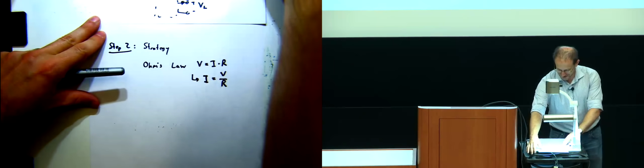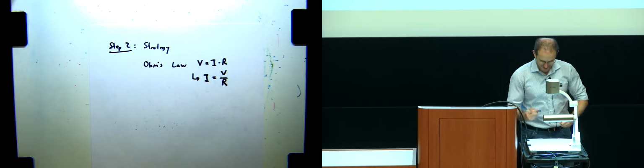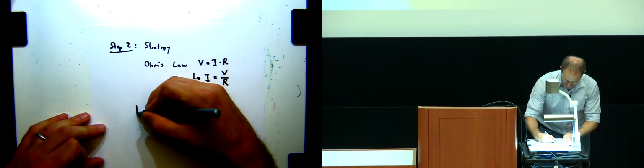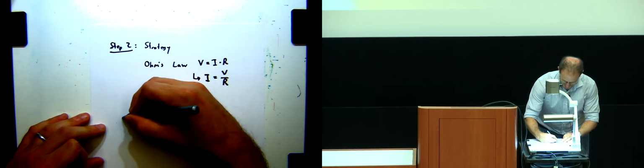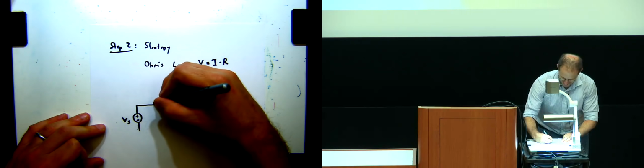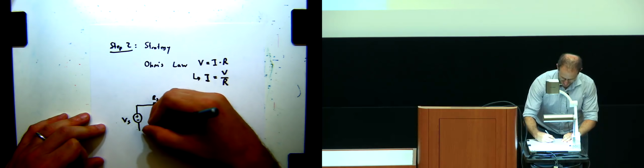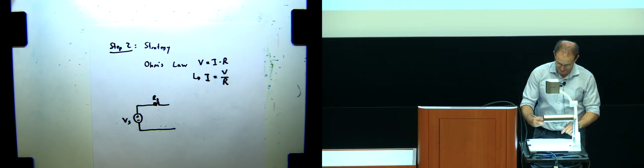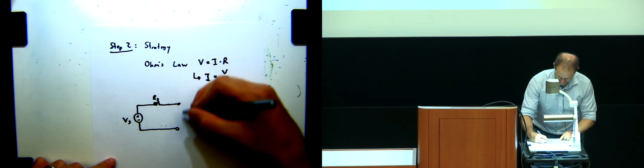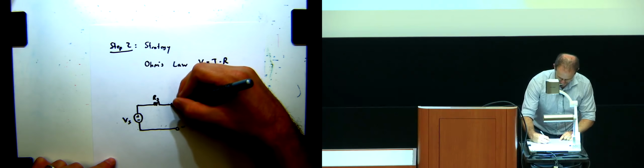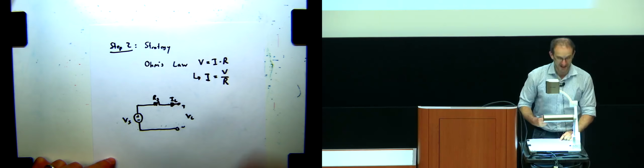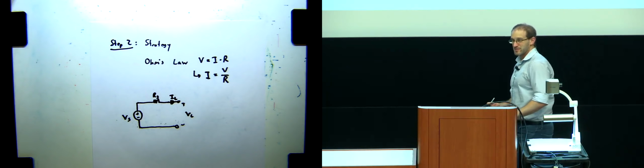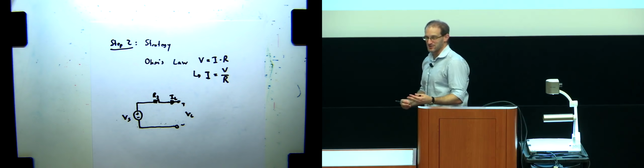So if our strategy is to somehow leverage Ohm's law, let's do the simplest, stupidest version of this. The simplest, stupidest version would be to say, all right, if I have a voltage source, let's say Vs, and some resistance, let's say Rs, let me take that black box that I drew before and just build it like this. And then say the output is over here, right? So there's some VL and some IL. So this is going to be my first attempt at building a current source.